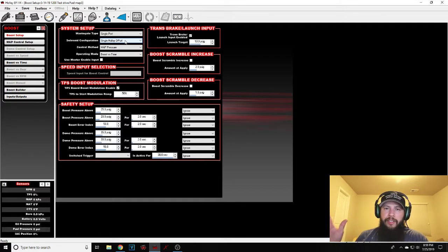That will max out any turbo setup. You want to know what your turbo setup will run, taking into account that exhaust pressure. If exhaust pressure is too high, then it's obviously going to give you a false signal. But let's say you have a perfectly efficient setup. Put one single boost line to the top of the gate. It's going to do everything that it can do until exhaust pressure pushes the gate open.